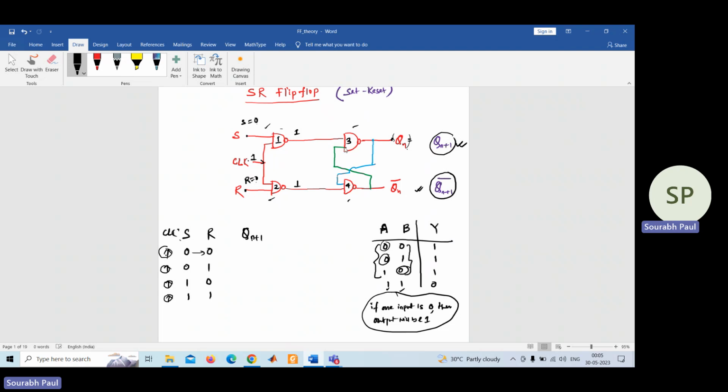You see in gate 3, what other input is applied at the other terminal? This is nothing but Q bar only that is applied to the other terminal of NAND gate number 3. And here 1 is applied. So what does it mean? What output will we get? According to the principle of NAND gate, Qn bar into 1 and it is whole bar.